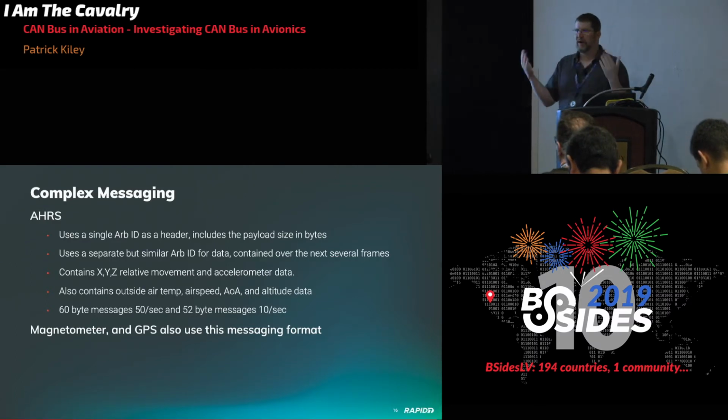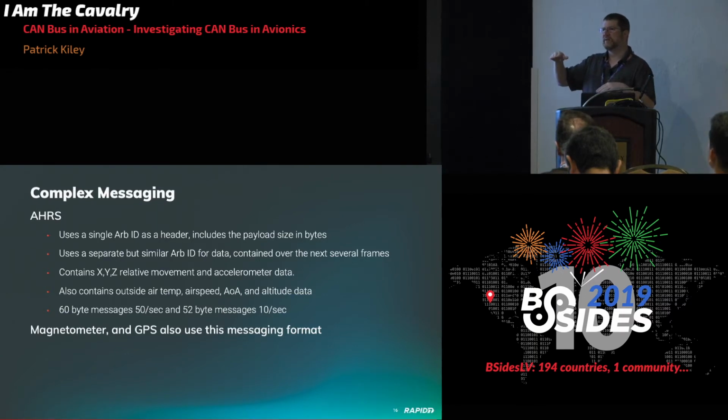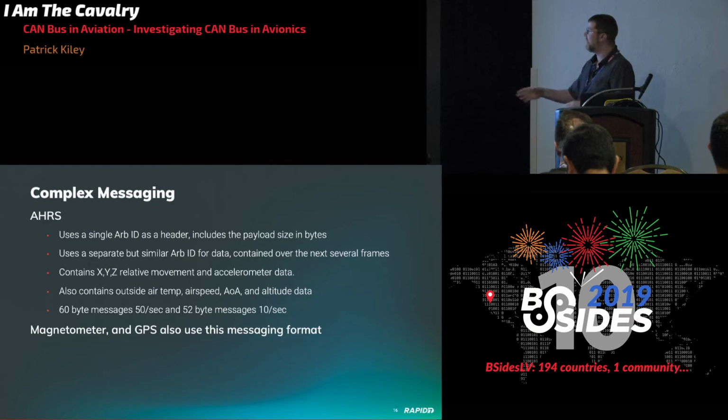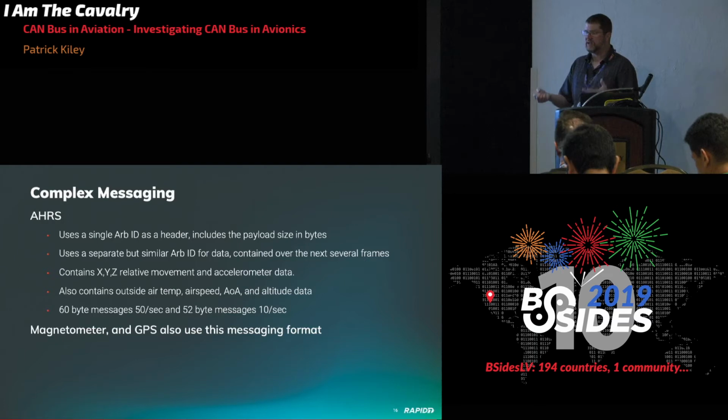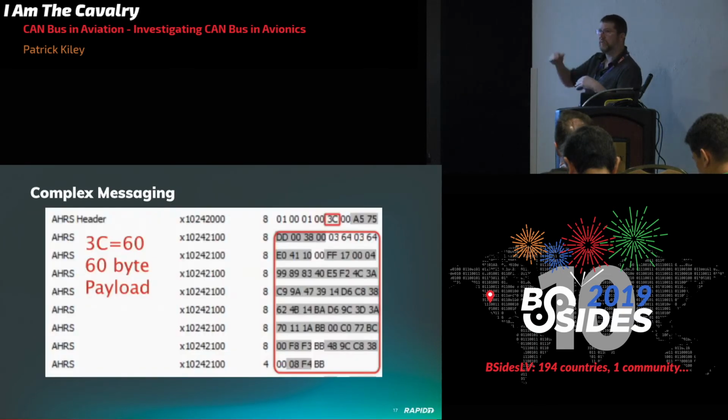And if you imagine you're a pilot, and all of a sudden your instrumentation is telling your aircraft you're pitching up, you're going to want to pitch down and compensate for that. If that's the only instrumentation that you have, it's going to be difficult. Now, typically aircraft have backup instrumentation, but some of the more modern ones trust everything that's coming in over this bus. If you imagine you're in IMC, which stands for Instrument Meteorological Conditions, so you're in the clouds, you have no reference to the horizon. Or if it's nighttime, you have a reduced reference to the horizon. And if your aircraft is telling you you're 1,000 feet higher than what you actually are, you could be headed for a bad day very quickly.